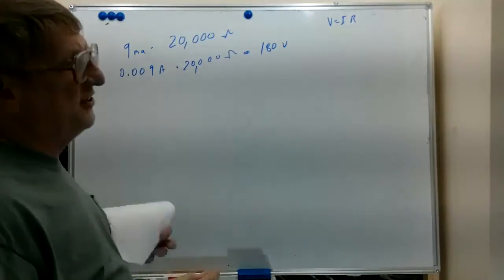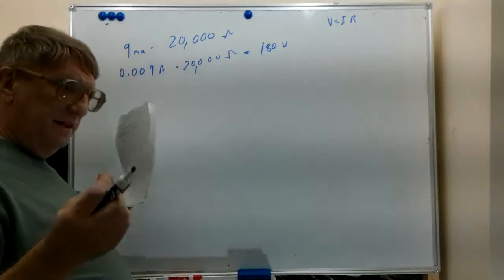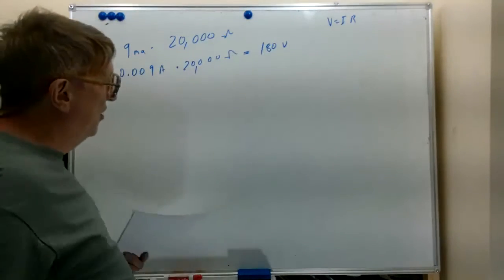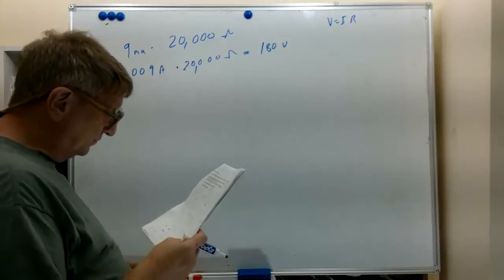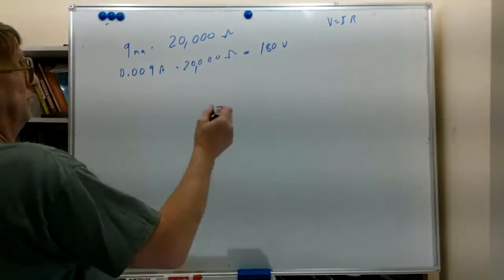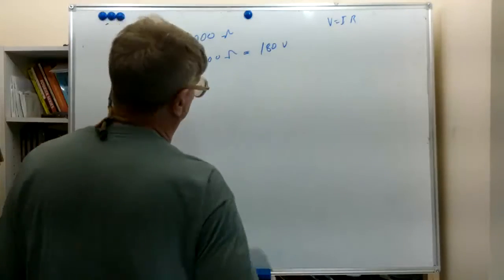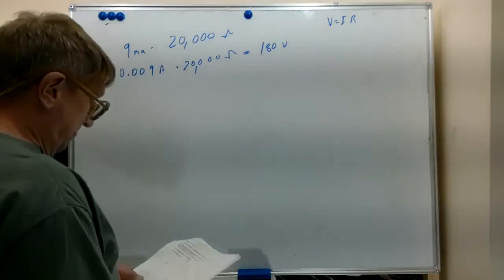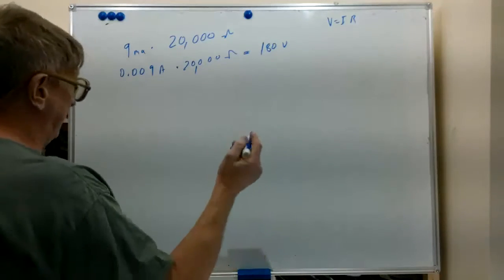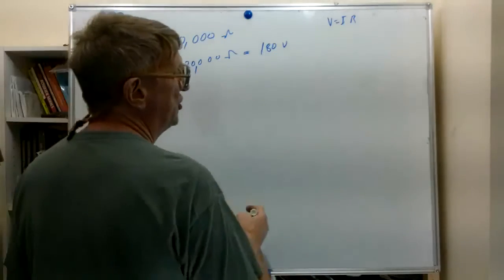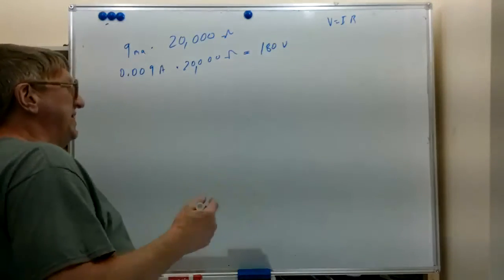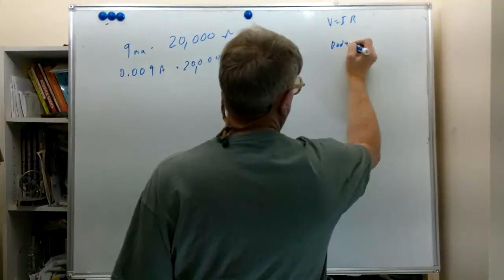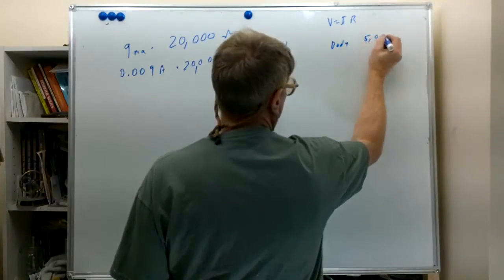So if the resistance you got connected across the circuit was 20,000 ohms, if you were at 180 volts or so, you've got a very good chance of getting froze on, being unable to let go. But let's just say worst case, or near worst case, that you're wet and sweaty and stand in a puddle, and maybe your body resistance happens to be 5,000 ohms.